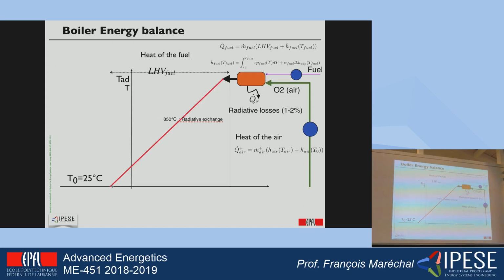Now, something that is important is that, of course, I could represent as a function of the temperature something like this, which is not in reality a straight line. Okay, it's a little bit curved because the Cp is not really a constant over a 2000 degrees C temperature scale. Okay, but I will represent it as a constant, and I will also have to recognize that when I'm doing the pinch representations, I'm mainly trying to represent the convective countercurrent exchange, which means that I will most probably not access this very high temperature operation here.